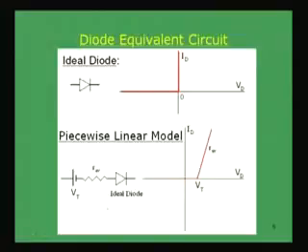that is why we are now getting 3 equivalent circuits. One is the ideal assumption, where the characteristic will become like this. That means it will be 0 up to when the applied voltage is reverse biasing the diode, it will be totally 0 current, and when it just increases beyond this 0, that means we apply forward bias, the current will rise immediately to an infinite value and there will be no voltage drop across the diode. So, this is the ideal equivalent circuit for the diode.